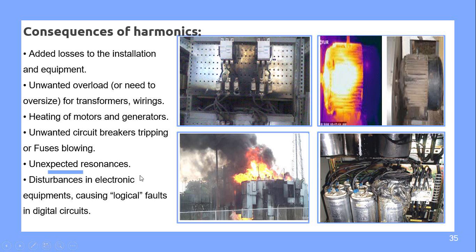So the consequences are added losses to the installation and equipment, unwanted overload, heating of motors and generators, unwanted circuit breaker tripping or fuse blowing, unexpected resonance, and disturbances in electronic equipment causing logical faults in digital circuits.